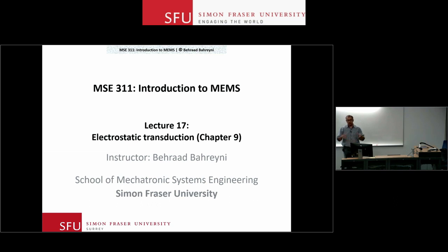But among all these different types of transduction, piezoelectric, piezoresistive, thermal, resonance, electrostatic transduction is the most common one, both for sensing mechanical displacements and also to apply forces to these structures. And then we'll see why this is such a popular method at microscales and what makes it so much better at small scales compared to large scales.